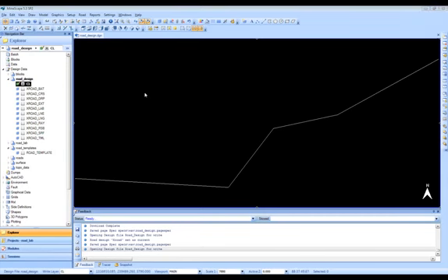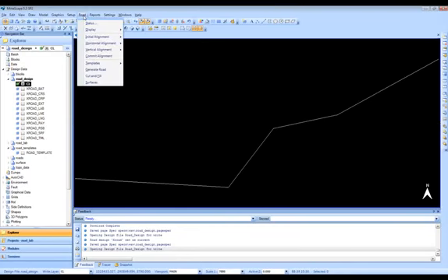Now, as I mentioned to you, road design is a fairly linear process, and under the road pull down, we've listed these processes in the order that you would perform them in. So you're going to perform an initial alignment. Basically, what is the center line? Defining that. Horizontal alignment, the vertical alignment. Then you're going to commit that alignment. We're going to apply some templates, generate the road cut fill projections, and then generate some surface.